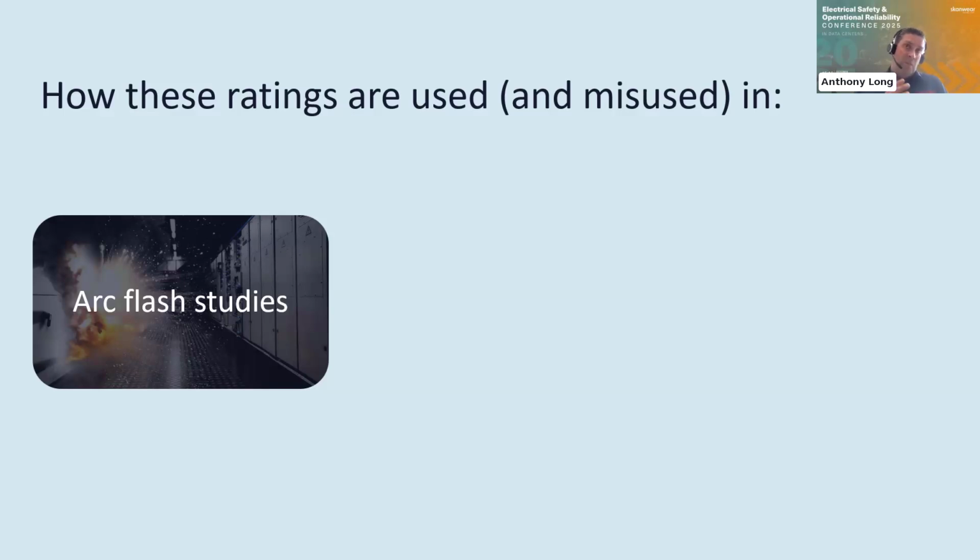Most day wear is over 8 cal. Normally, you're layering up to achieve 25 cal. To wear 25 cal as your day wear, let's say I'd rather not wear that. There are some lighter garments in the marketplace. We're bringing new lighter articles out. But in the main, arc flash studies should just say a cal rating. You interpret that cal rating however you need to. Look at where you need to do most of the work, where most of it is carried out, and look at a layering solution that fits in with your system. Don't revert to category, and obviously don't refer to class. There's no correlation between the two of those.